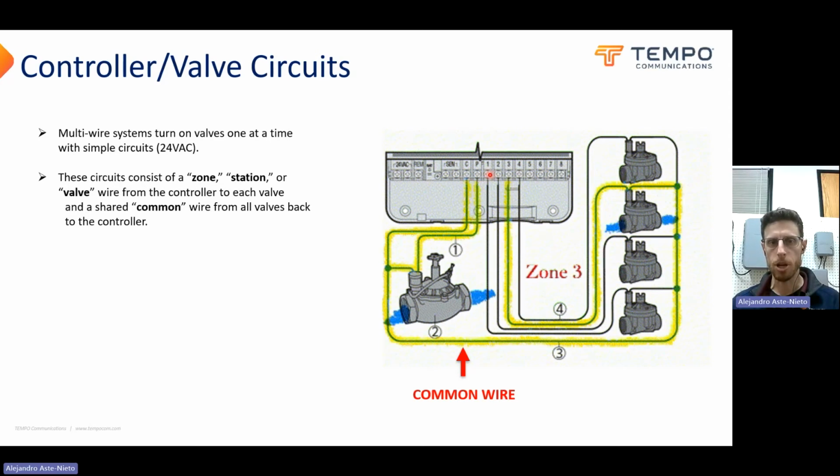If there's high pressure here and low pressure there, these other circuits are not affected. The movement of electricity is going to flow from the high pressure to the low pressure and not really take any detours. So you can use one wire to share between all the valves, and you can still turn them on one at a time. That's why it's called the common wire.